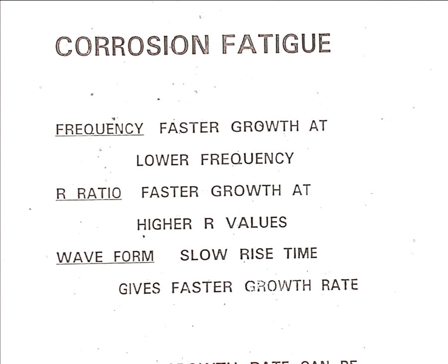So you have to test the material at the same speed as it's going to experience in real application. And quite often that's something like a marine environment, and the frequencies are something like 0.1, 0.01 hertz. They're quite low frequencies. So the testing takes time.